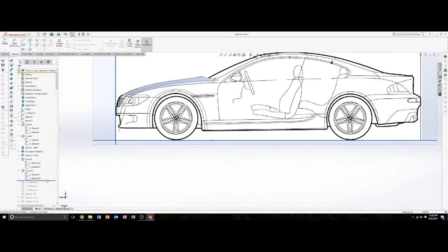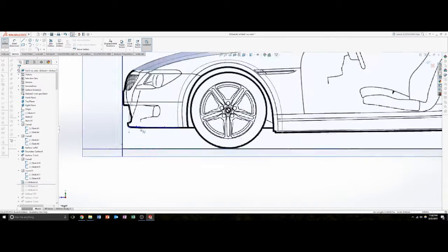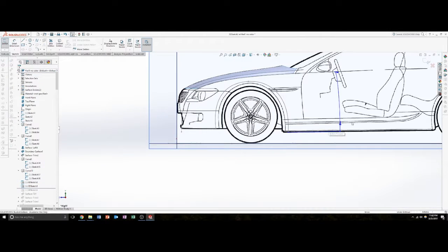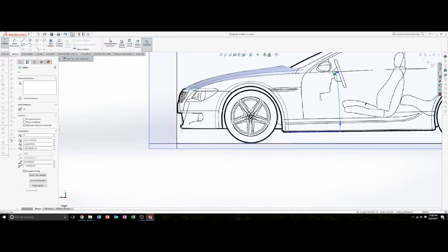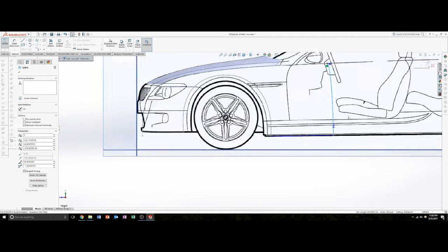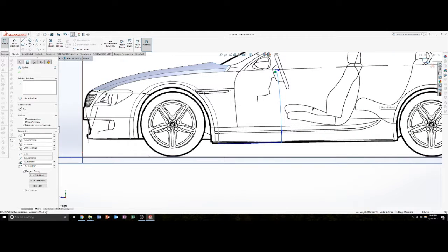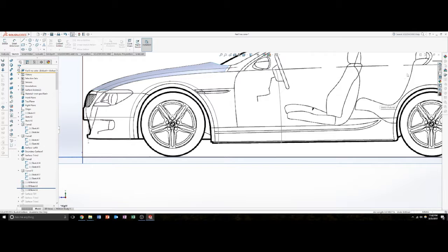In order to create a filled surface, another 2 3D splines will be required for the patch boundary in the filled surface feature, as well as the 2 curves we made before. When you are creating the 2 3D splines to connect the 2 curves, make sure the endpoints of the curves and the 3D splines are coincident so they make a closed surface. Otherwise, SOLIDWORKS will pop up errors.